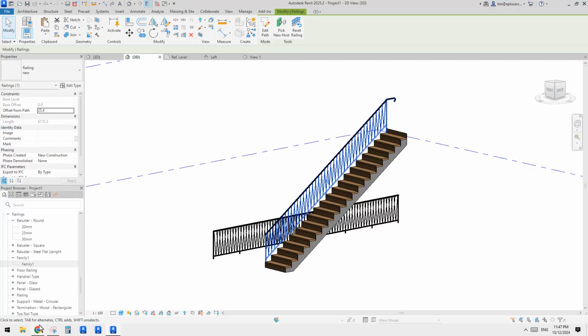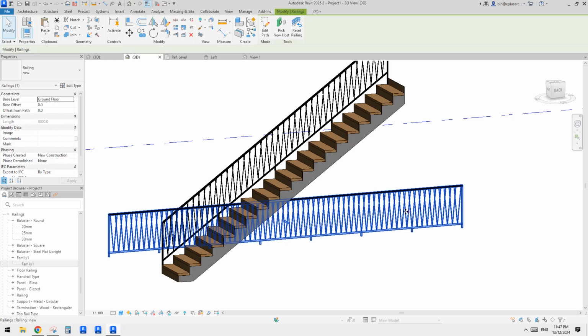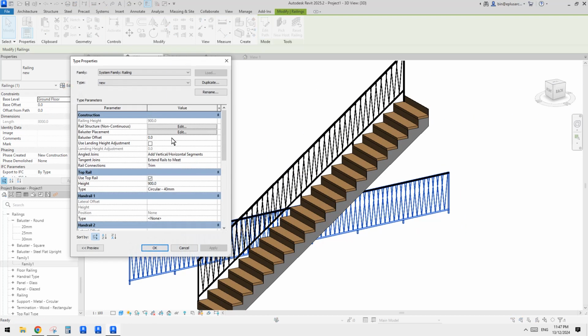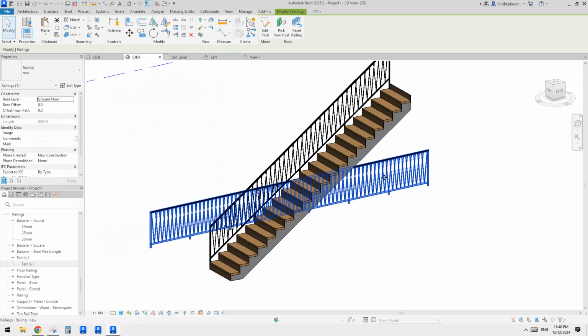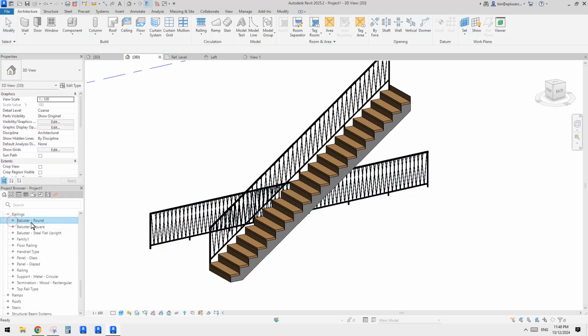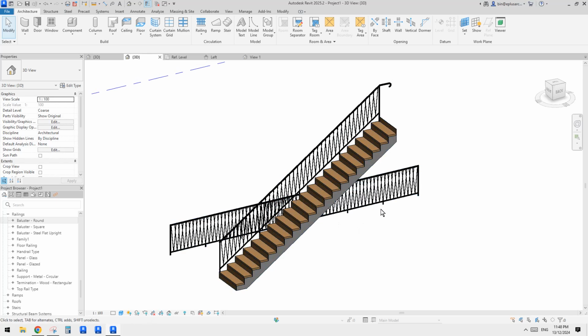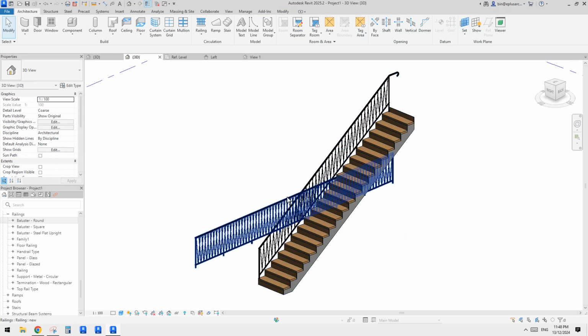I think that's all. It's very simple. You just need to know where all these settings are. Balusters are all the vertical members. All the horizontal members are either the top rail or the railing structure here, which are non-continuous. Also, all these baluster families, once you load them into the project, are under Family, under Railing. So these are all the settings. You need to find the right one so you can adjust them. I will upload this family for you so you can have a look.